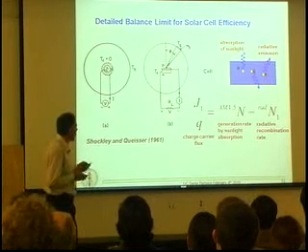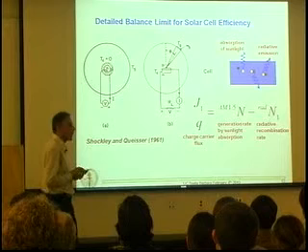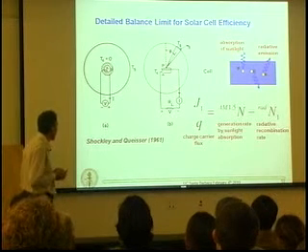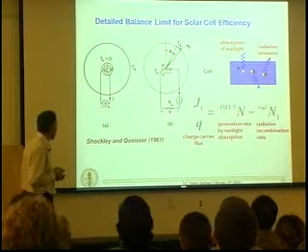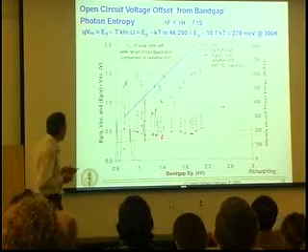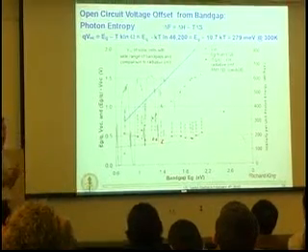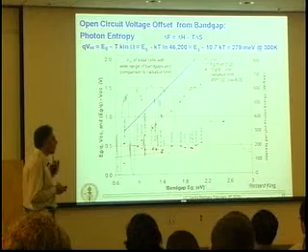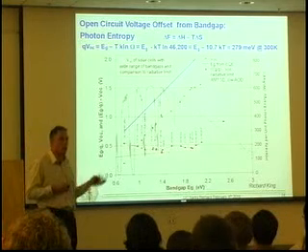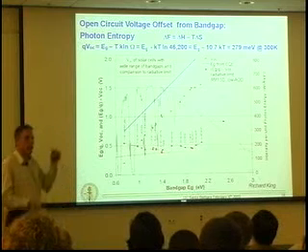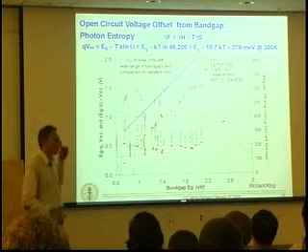But this is really a pretty fundamental limit, and it allows you to define the limits to conversion efficiency for everything else being ideal. The other thing that is kind of interesting that defines an efficiency limit for a solar cell is how much of the bandgap energy is available to us as a separated charge potential in the external circuit, since we absorb light across a bandgap in the semiconductor.